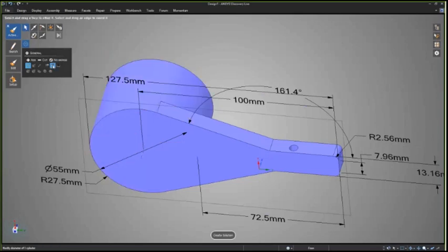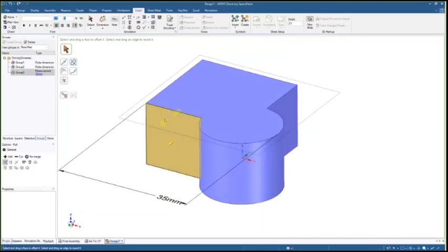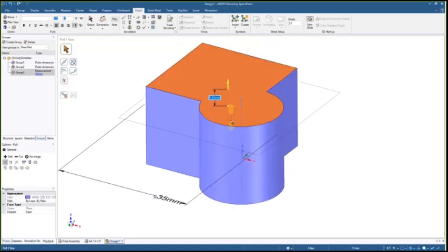You can even use mass properties to drive the model. So if you want to do it by mass, you actually have to do it in SpaceClaim. If you want to do it by volume, you can do it in either. The reason for that is models need a material property set here for volume. So for example, I want to maybe pull this face up.